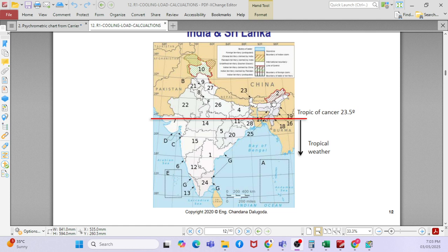If you talk about some of the FAHU, you have an enthalpy wheel, then a cooling coil, then also a sensible wheel. But still, after that, you may not be able to achieve the required temperature. Then you will try to increase the temperature by adding a heater.